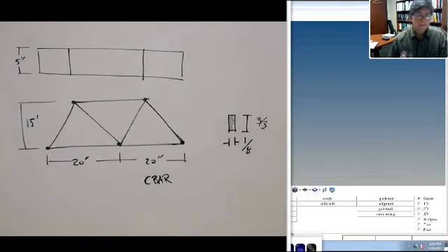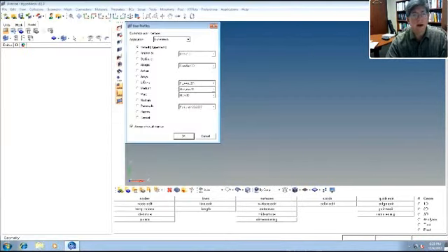Now, when you make the file in Hypermesh, one of the good things you might want to do is follow this approach. The first thing, as I mentioned, is that you can use this to support a lot of different finite element codes. We're going to use Nastran, so pick Nastran. This is what's called the user profile.